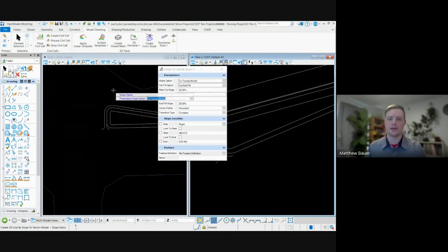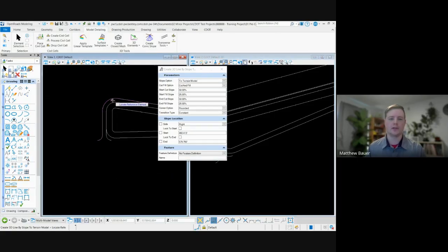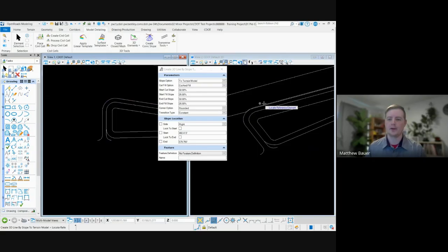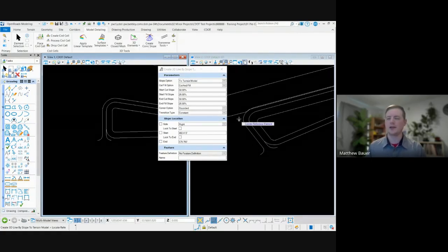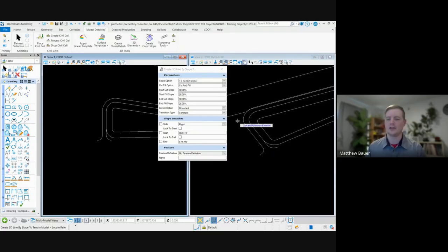You can see the boundary up here. I want it to cut and fill whatever it has to do. I've specified what slopes I would like: 2-to-1 cut, 4-to-1 fill. Perfect. So I'll flip through here. What's my reference? I have the ramp on the backside, but all of this I want to be grading. And I don't really want to have to draw it and make sure it connects to existing ground.